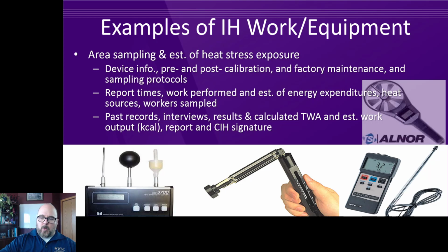Over on the right, we have a velometer. The one on the bottom is a hot wire anemometer. The one on the top is a repeller. With the hot wire anemometer, as air flows over the heated wire, the rate at which it cools is turned into a velocity.